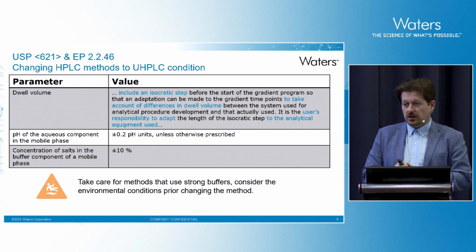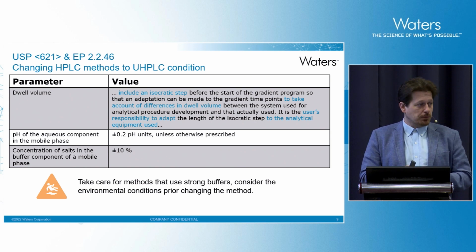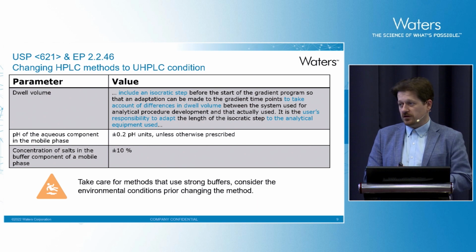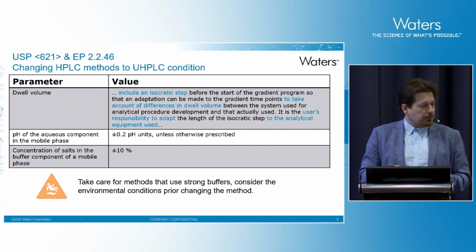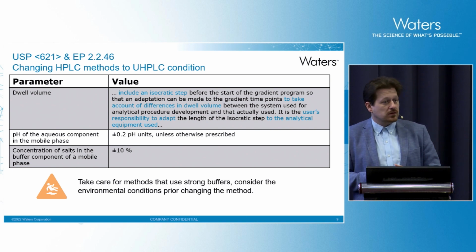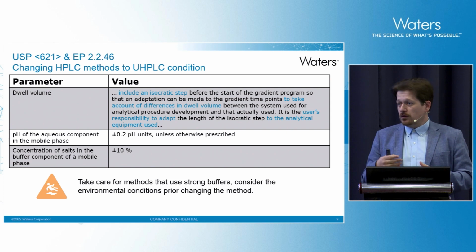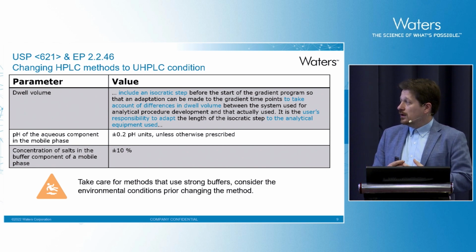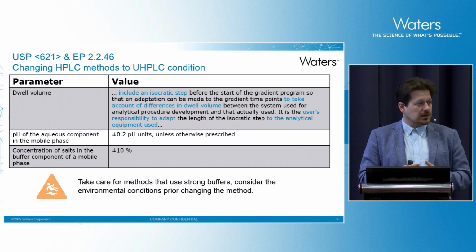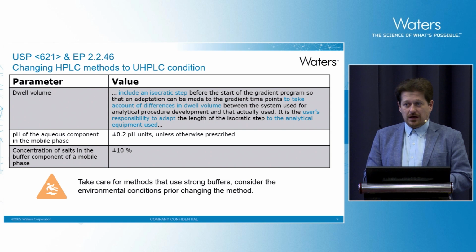The first reason is that if you work with highly concentrated salts on a narrow system volume instrument, and you forget to flush it properly after use, you have a certain risk of crystallization. It could be that in the lab at night it's cold, if there is no flow, it could happen, and we don't want something to crystallize in the system. On the other hand, if you have very good SOPs in place and processes so that after the method was performed, you automatically flush the system with another sequence, clean the column and so on, then it shouldn't be an issue. This is one aspect. The second aspect is the column itself. Not every UPLC column that exists on the market likes high salt concentrations.